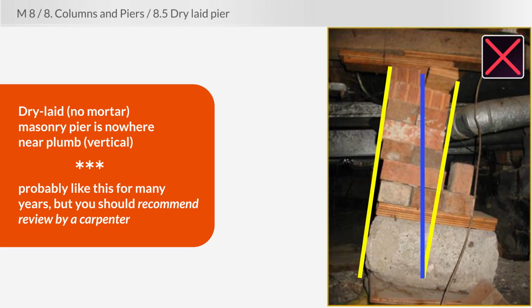Repairs like this, the biggest expense is going to be for the labor because some poor carpenter has to get down in this crawl space, temporarily shore up the house, remove this mess, add a proper post, remove the temporary shores. Just going to be a major pain for him. And so the cost is going to come from all the labor, not from the material.